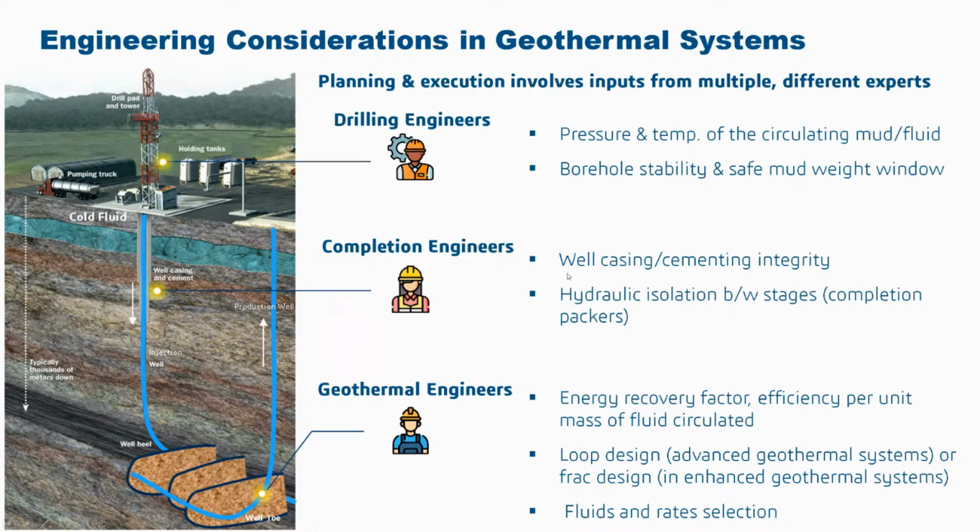Completion engineers are responsible for putting well casing and cementing. They're also responsible for putting hydraulic isolation if required, or plugging of the well upon the end of the life cycle. Then you have geothermal engineers. Geothermal engineers are responsible for ensuring that there is a high energy recovery factor. They're responsible for maintaining the efficiency per unit mass of the fluid circulated. They're also involved in the loop design if you're thinking of advanced geothermal systems, or frac design if you're thinking of enhanced geothermal systems. They're also responsible for fluids and rates selection.